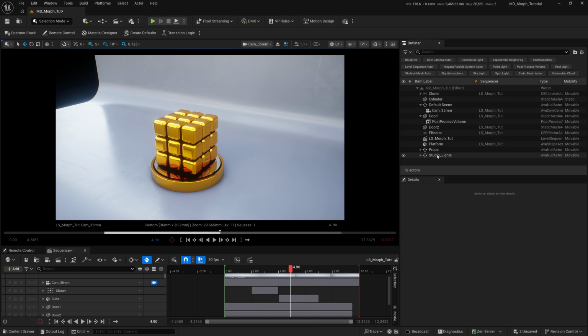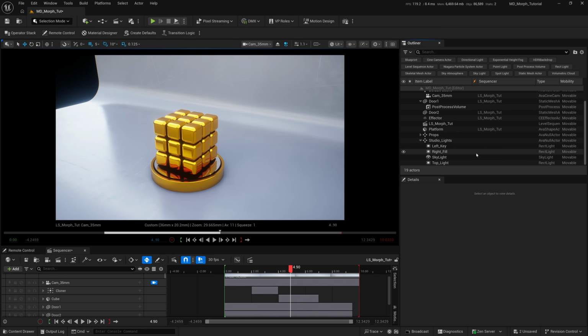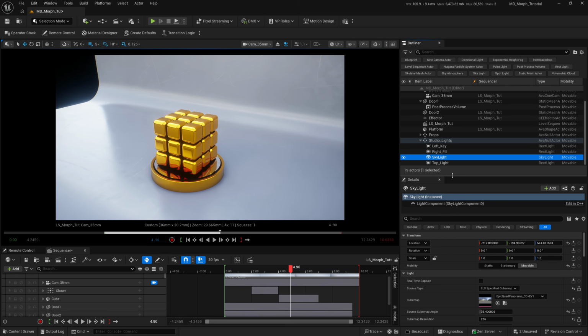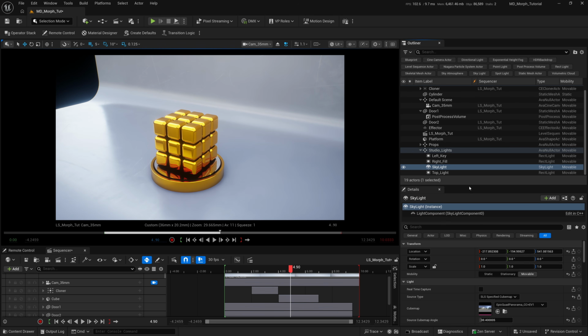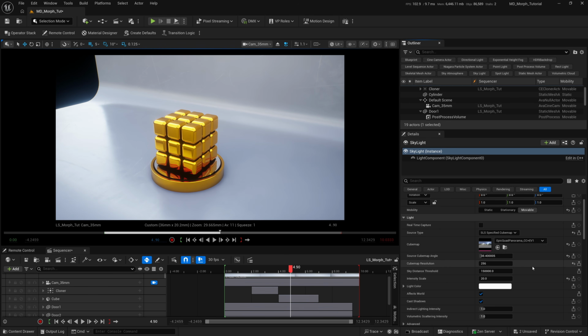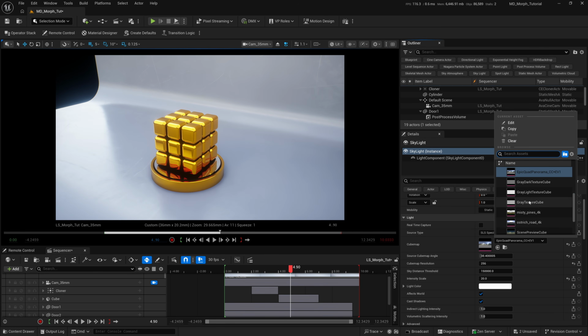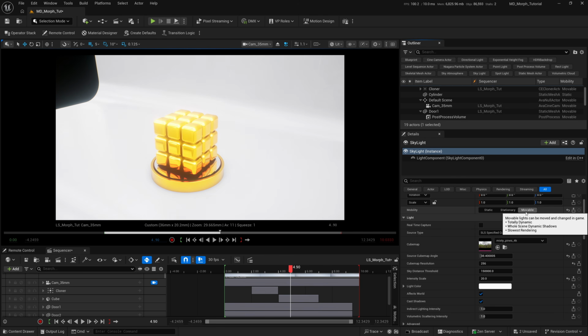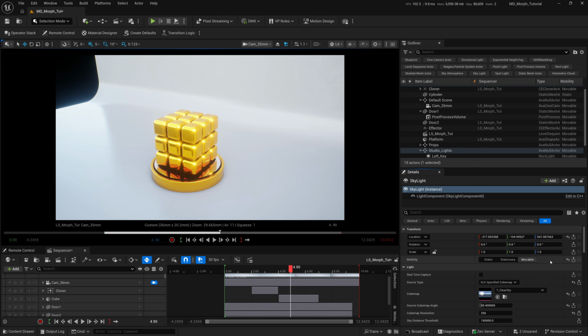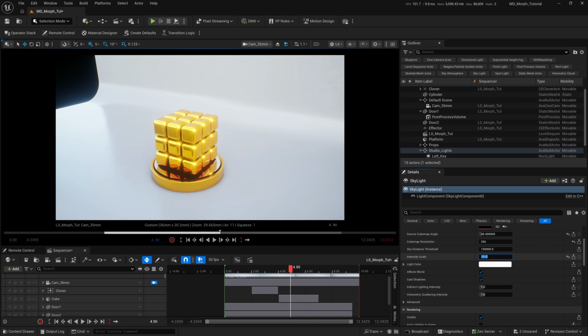And what we're going to do is we're going to select the skylight. Okay, the skylight is made out of a HDRI. If you scroll down, you can see it's actually from this Epic Quad panorama. You can actually change this to whatever you want. So let's play with this. So maybe try this Misty Pine so you get a different kind of color. Not that bad. And then we can bring the lights down a bit. So in the skylight, we can bring down to maybe 10.